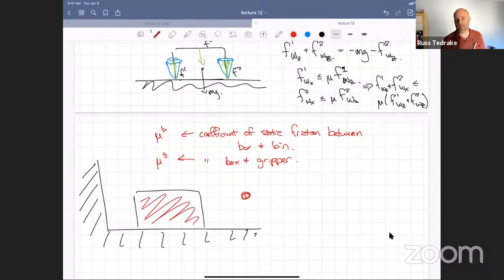There are some really nice things about force control. In fact, even in walking research, we tend to use force control quite a bit. If your walking robot is force capable, you will tend to see people use position control mode, using the PD controller and the inverse dynamics controller I just described, while the robot's leg is swinging. I know you can't see my leg, but imagine my leg is swinging, and I want to have my foot in a certain position in space. So you would put the swinging leg in a mostly position control mode.